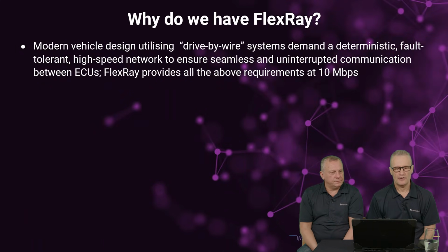So why do we have FlexRay? Modern vehicle design, again, isn't it? It's forcing us to go this way. We need faster networks. Drive-by-wire systems demand a deterministic, fault-tolerant, high-speed network to ensure seamless and uninterrupted communication. FlexRay provides all the above requirements at 10 megabit per second. So we think we've got it accommodated, and I think we have, but we'll see as we move on through this series of videos.